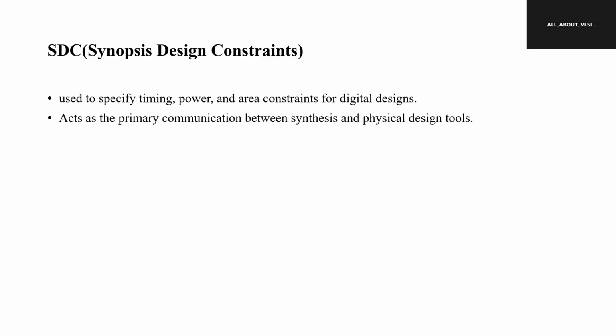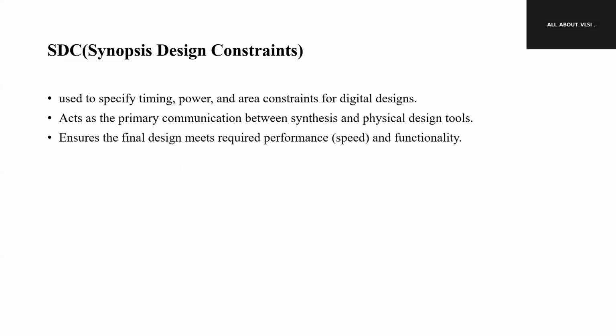At the synthesis stage we are defining the clocks, which means we are creating the clock, we are creating input delays and input transitions, we set the delay, set the loads. So all the information is present in this SDC file, which ensures the final design meets the performance, which is completely related to timing, how much speed it will work. So it completely depends on timing, right?